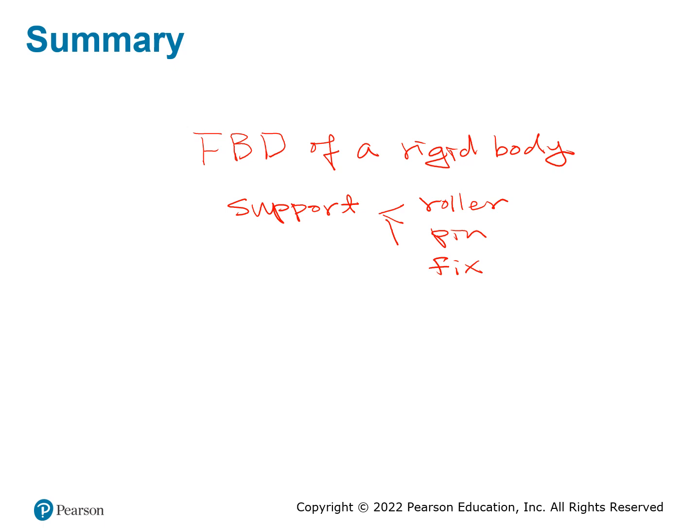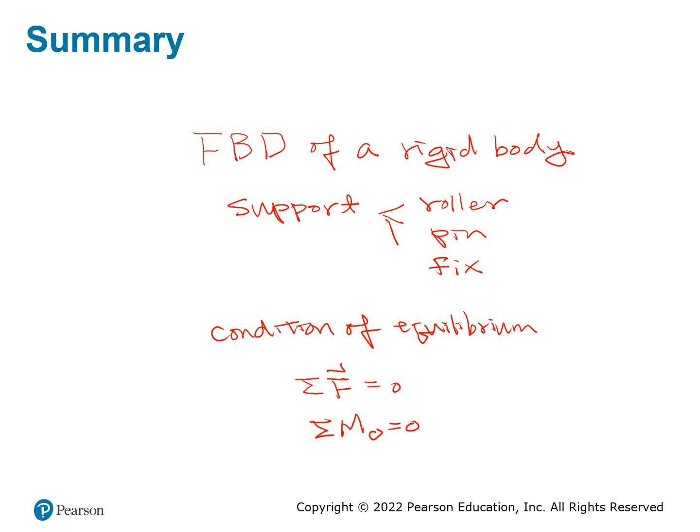The second thing we talked about is the conditions of equilibrium. We have the summation of F equal to 0. We have the summation of moments about any reference point equal to 0. And those are the equations that you need to solve this problem.